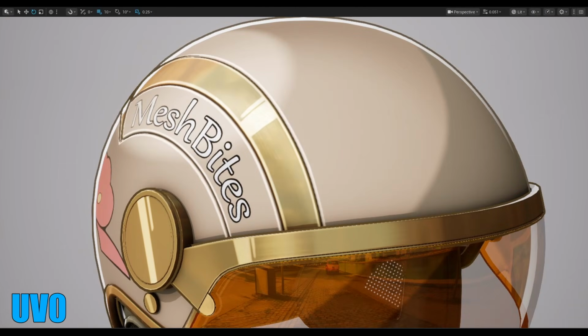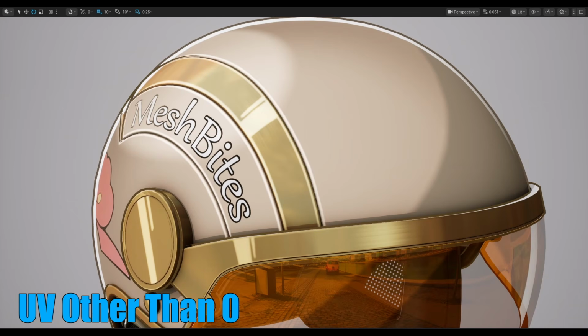By default, Unreal Engine uses the tangents generated from UV channel 0, so the tangent direction is closely tied to the UV layout of that channel. It is possible to use a secondary UV set to override or control tangent direction, but depending on the effect and texture resolution, artifacts may become more noticeable. For the best quality, I generally recommend using UV0 whenever possible.